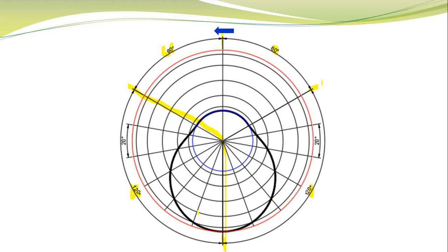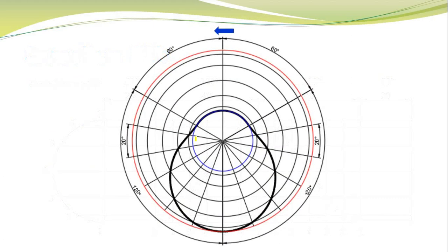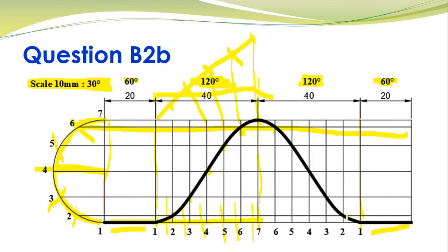Now the next thing is how I get these points in. So getting these points in is very easy. So basically from here to here, the cam was rotating and there was no movement of the follower. It remained stationary, so dwell. Then from 60 degrees onwards, the follower moves outward for the next 120 degrees of rotation of the cam. So this point over here is basically a point over here, right? So your minimum cam radius is basically indicating this benchmark over here.